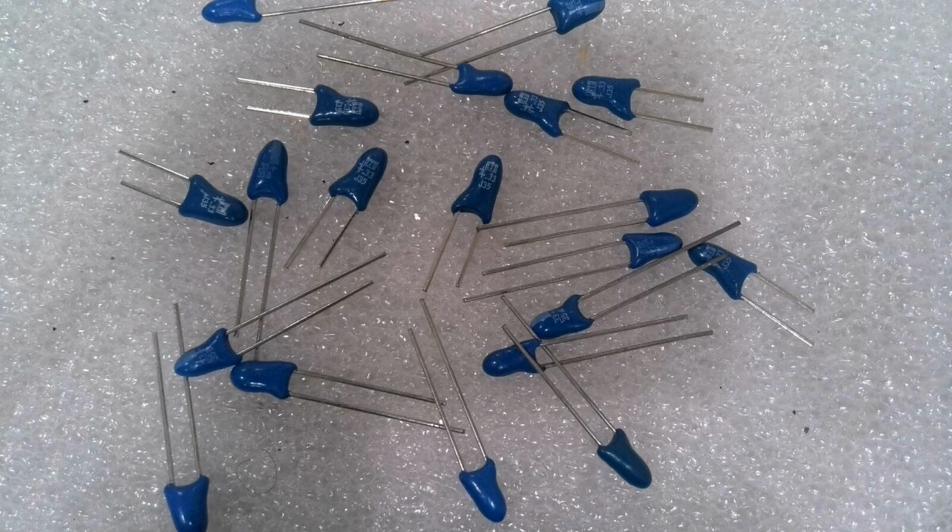Low impedance and ESL. Suitable for high-speed and high-frequency applications. Durable and long-lasting. Resistant to drying out and mechanical stress. Reliable in critical applications. Used in medical devices, aerospace, and automotive electronics. These advantages make tantalum capacitors highly suitable for demanding applications requiring high reliability, space efficiency, and stable performance over time. However, they are sensitive to reverse polarity and high voltage, which can lead to failure, short circuit, if not handled correctly.